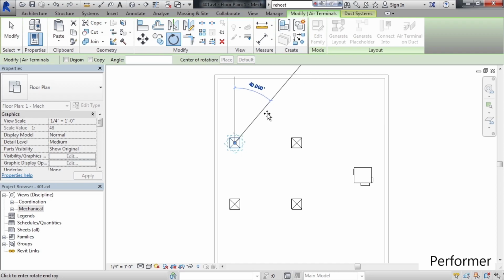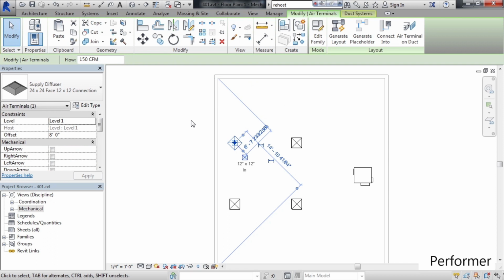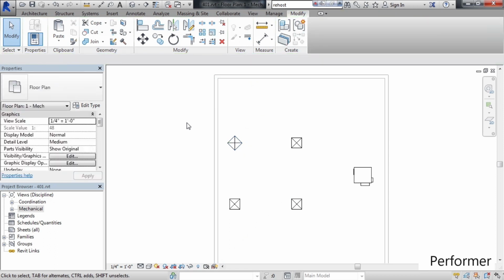This is now how far you're going to rotate and in the direction you're going, counterclockwise or clockwise. So let's move the mouse in a clockwise fashion until you see 45 degrees, or you could key in whatever angle you want. Once you see the angle, such as 45 degrees, go ahead and left click. After you do that, it rotates your object 45 degrees about the base point.